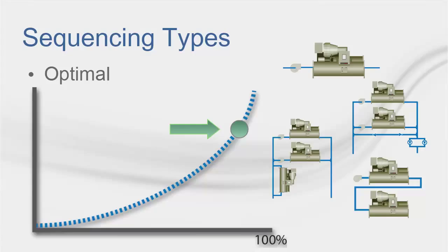It is very important to note that in order for multiple pieces of equipment in a plant to operate, no matter what sequence type you've chosen, the capacity for all but the final chiller must be entered. For example, if you have two chillers in a cooling plant, chiller 1 must have a capacity entered in order for chiller 2 to see any load. If chiller 1 has a blank capacity field, Trace will not know what the maximum capacity for that chiller is and will size it to handle all of the load.